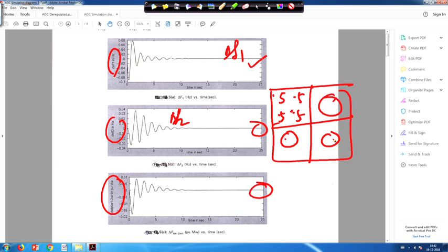Here all are 0, so there is no question of scheduled tie power flow. For this case you can easily evaluate that delta P tie 1 to 2 scheduled is equal to 0, and error is equal to actual minus scheduled. So, as scheduled is 0, delta P tie error will be equal to delta P tie 1 to 2 actual.